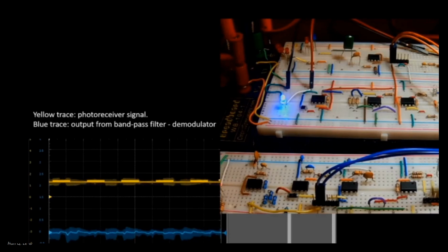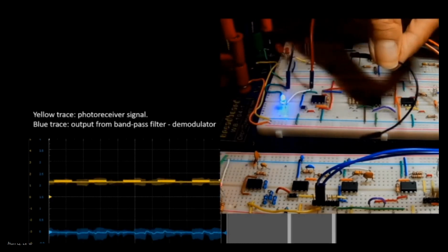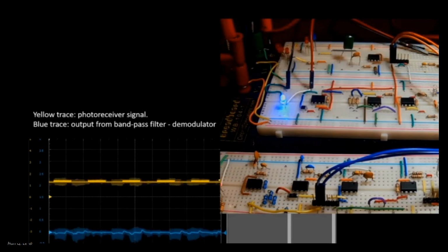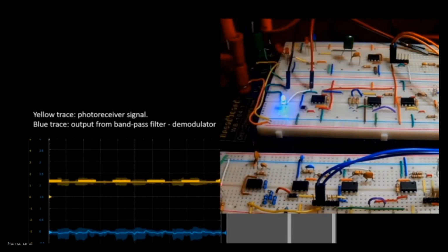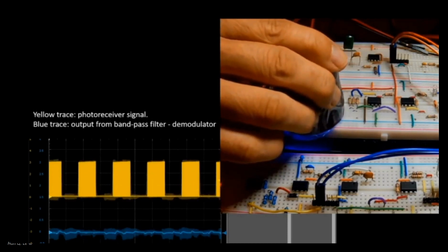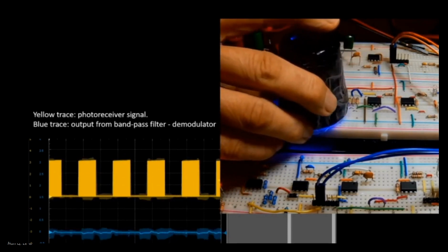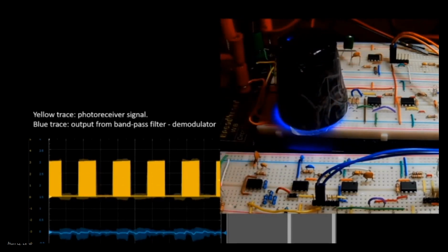The LED transmitter is driven by a simulated signal and its light output is coupled to the nearby photodiode. A small enclosure enhances the coupling between the LED and the photodiode. The photoreceiver output shows a 100 Hz square pulse that simulates a message, which is modulated at a 9.3 kHz square wave.